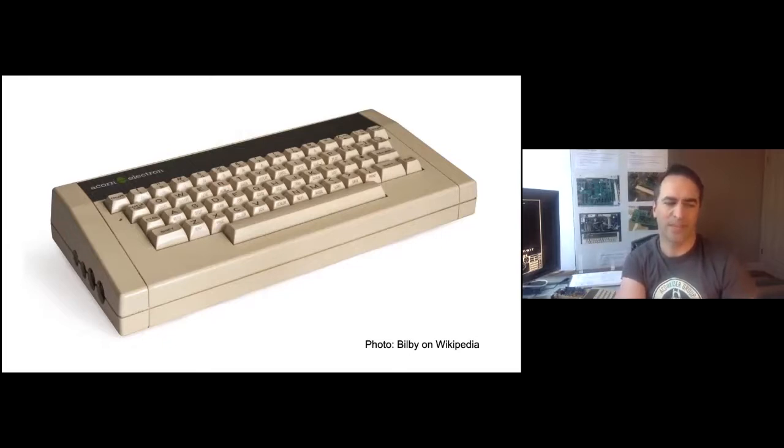The tape is more or less what it is in the BBC, I think, but instead of a whole ULA just for the tape, it's just a little bit of this one. The keyboard is a little bit weird. The columns of the keyboard are wired up to the CPU's address bus, something I've never seen before. And then the rows go back to pins on the ULA. And then the disk interface is gone, Econet's gone, no user port, no Tube. The 1 MHz bus is sort of still there, but not quite in its same form.